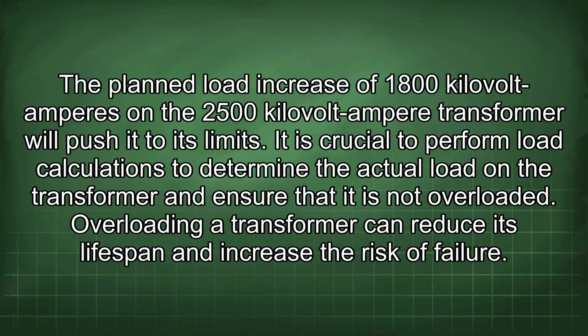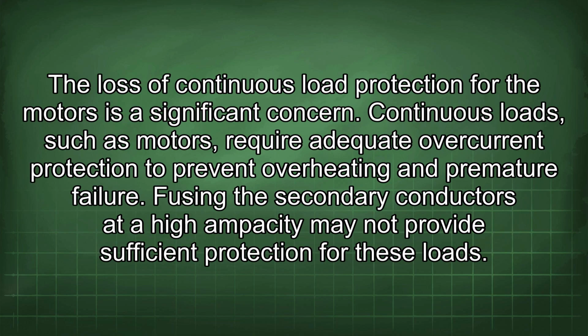It is crucial to perform load calculations to determine the actual load on the transformer and ensure that it is not overloaded. Overloading a transformer can reduce its lifespan and increase the risk of failure. The loss of continuous load protection for the motors is a significant concern. Continuous loads, such as motors, require adequate overcurrent protection to prevent overheating and premature failure. Fusing the secondary conductors to high ampacity may not provide sufficient protection for these loads.